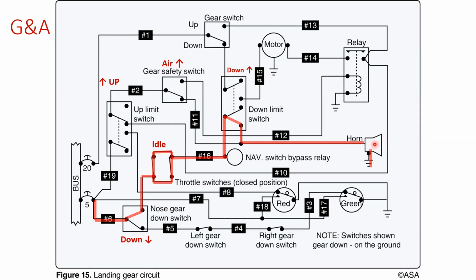So this just lets the pilot know that, hey, your gear is not down, but your engine power has moved to the idle position, which makes me think you're getting ready to land. And it's going to give a warning saying, hey, you need to extend your gear because we do not want to land with the gear up.